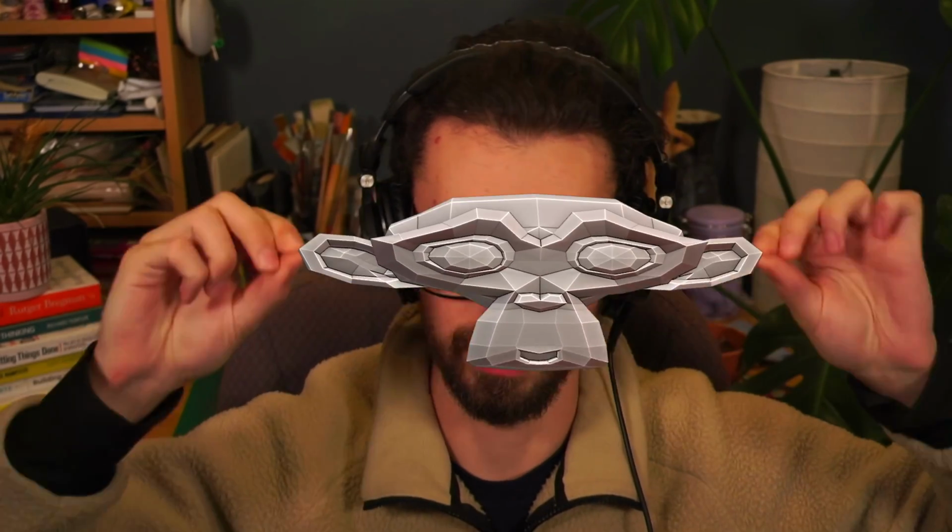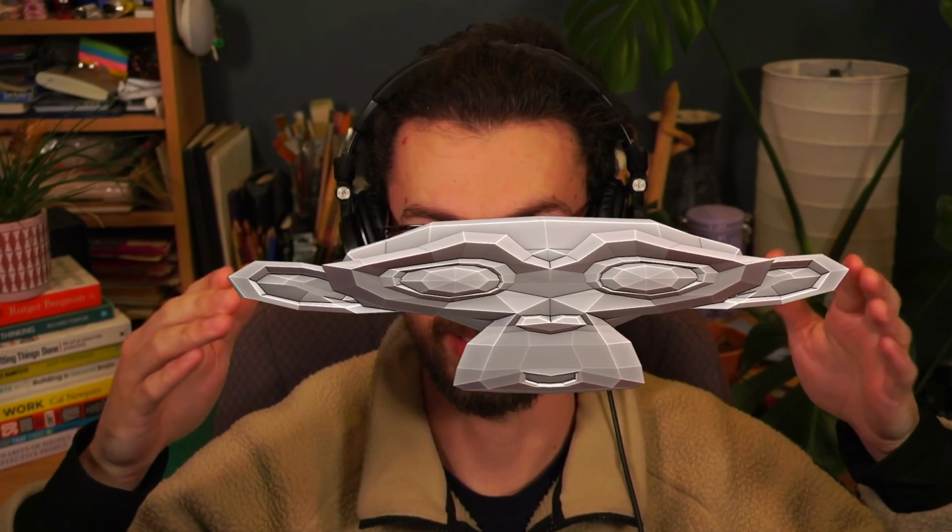And now we have the third part of this idea, where rather than an entire collection, what we're going to be doing is picking an object from a collection and instancing one object per curve. Not deformed, just basically creating a single edge, and instancing on that edge with our object scaled and rotated to align to the edge. There's a little bit of additional logic in here for us to make it into a higher level tool.